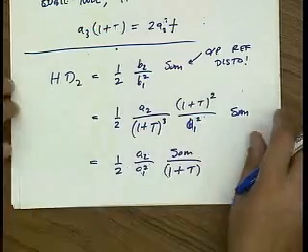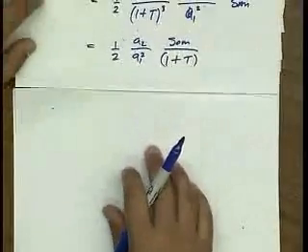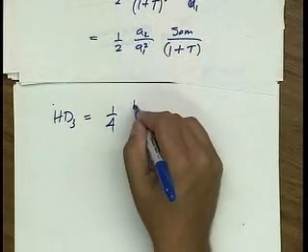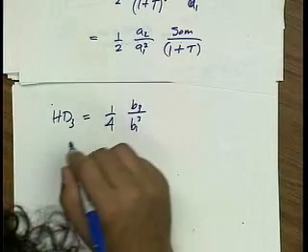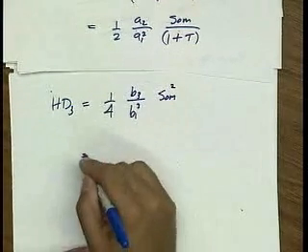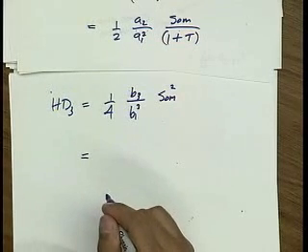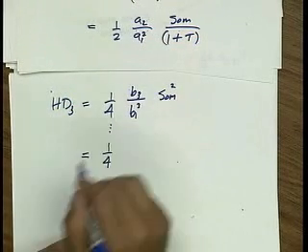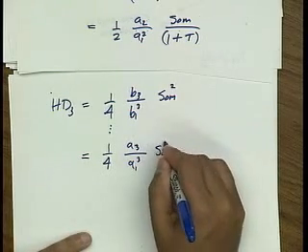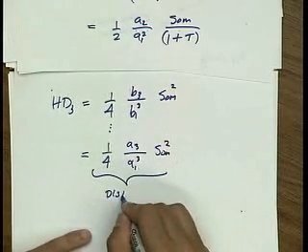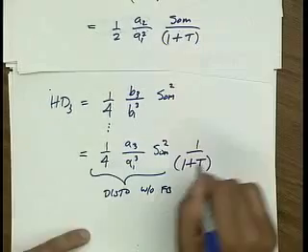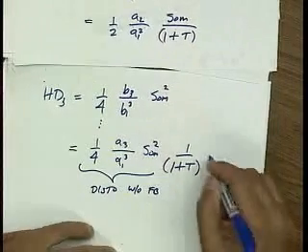Okay, very good. All right, so that's HD2, let's look at HD3. HD3 we derived last lecture in terms of the output is b3 over b1 cubed times the output level squared. Okay? And I plug in all the equations that I derived. Again, I won't bore you guys with algebra. And the answer comes out to, I like to write the answer in terms of the distortion of the circuit without feedback times 1 plus t.